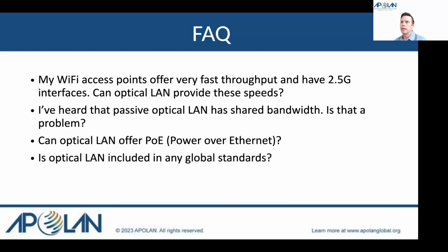The GPON and XGS-PON standards, the communication between equipment, are handled by the ITU through the G.984, 986 standards. And then we also have the standards around cabling and installation. The TIA 568C standard started addressing optical LAN with the C version, and we've seen that progress since then. We've also seen the BICSI TDMM installation manual address it as well. I think starting with version 14, if I recall correctly, the TDMM also covers the installation of this equipment. So really from the inception and the cabling and the installation all the way through the electronics and how they intercommunicate, those are all governed by global standards.